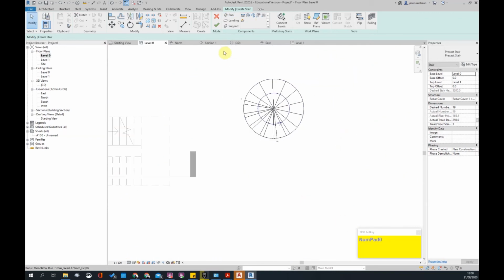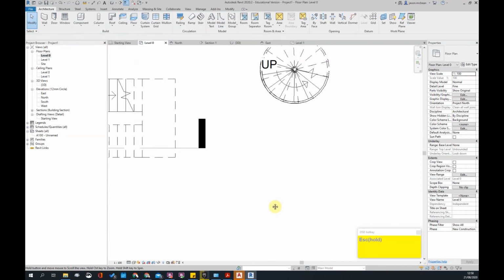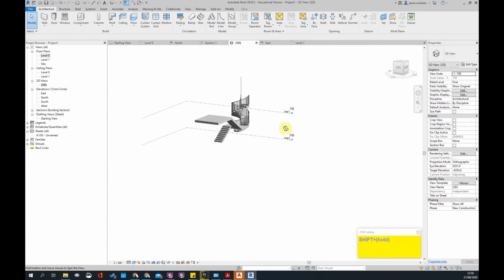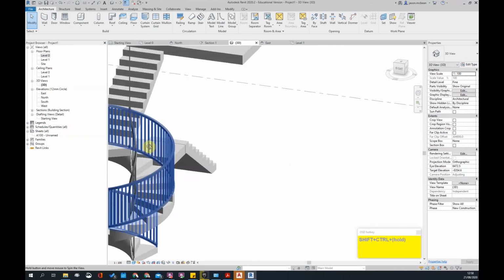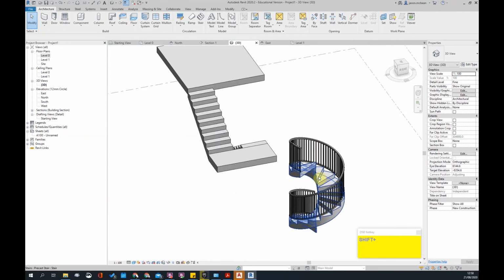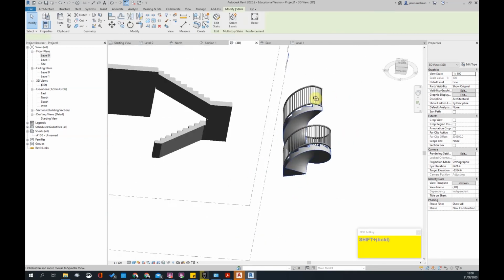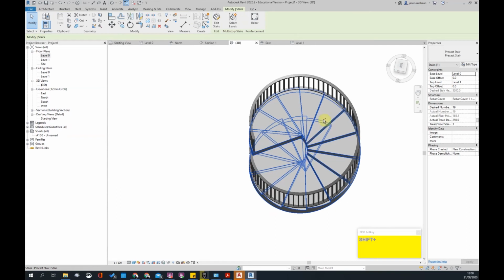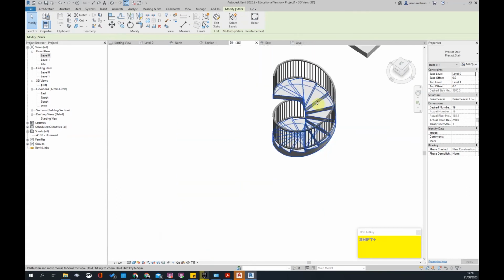Now what it does is it creates a, let's go 3D view. This creates a spiral staircase. Okay, these handrails on the side never really work because it goes up a pipe, so that's what I usually try and get rid of. But in essence, that's how you create a spiral staircase. And I'll use a structural column down the middle as my railing in essence.